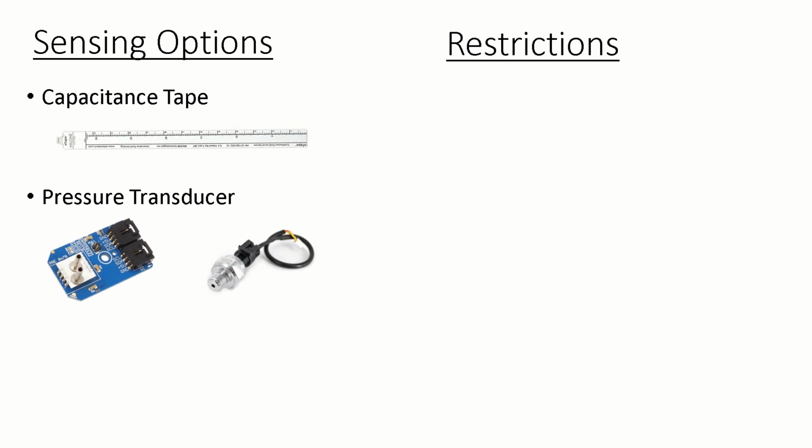Once a multitude of possible locations were identified, alternatives for sensor development were evaluated. The 3 design considerations were the following. A capacitance style sensor returns a depth of water contacting the sensor strip. This type requires submersion in the flowing region. Another option was a pressure transducer located at the bottom of the pipe or manhole. The depth of water would then be determined by calculating the force applied to the pressure sensor and correlating to depth. Finally, ultrasonic distance sensors were considered, which use sonic waves to detect the distance from the nearest object. These would be mounted in the manhole or pipe and provide the distance to the water surface level, allowing for a depth measurement without any submerged parts.